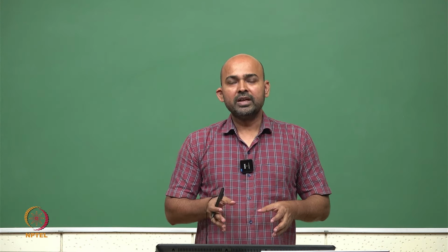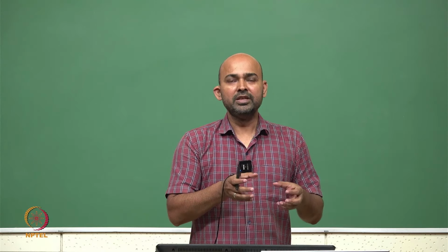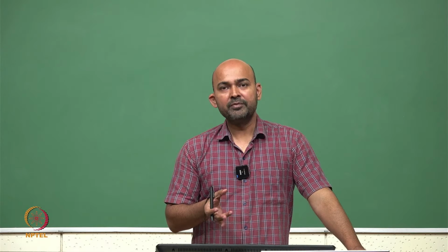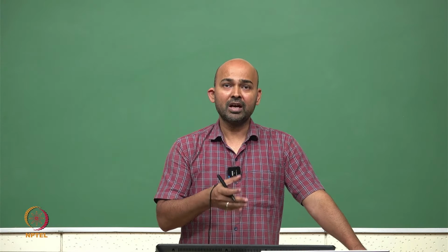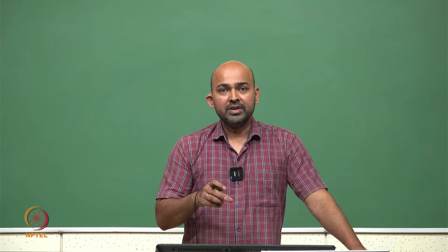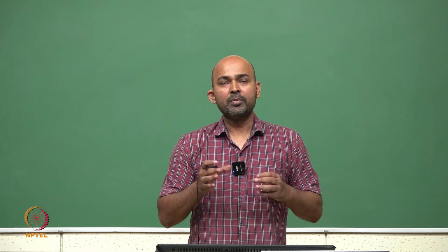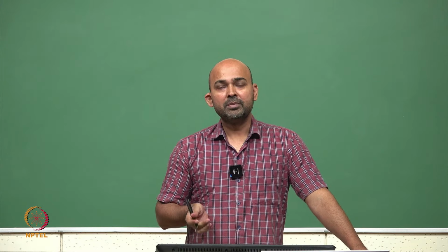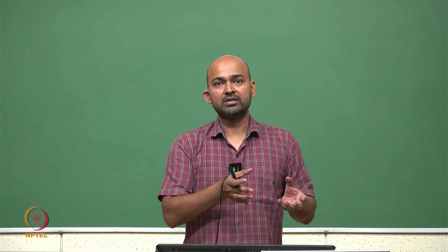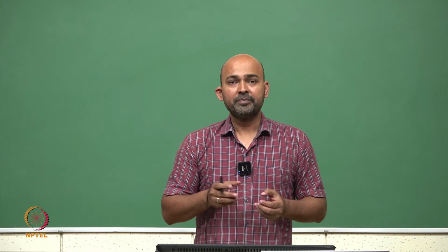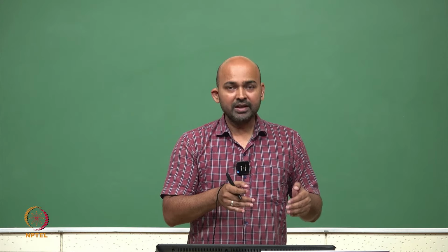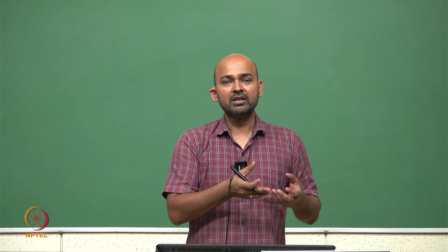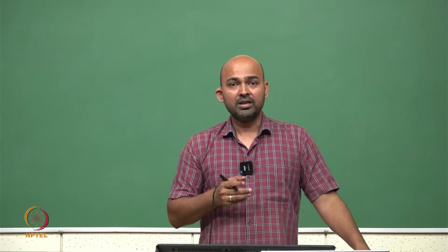So we saw today that some points need to be taken care of while designing RF PCBs, and we saw an RF PCB schematic where we are developing an RF power amplifier, which is a large signal circuit and operates at very high frequencies such as 1 gigahertz or above, and this is the PCB designed for that particular power amplifier schematic. And we saw that there are certain factors we need to take care of in RF PCB design which are generally not there in high speed PCB design, such as the bond wire inductance.